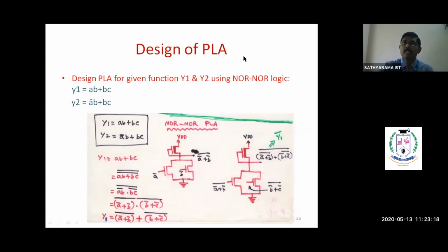Okay, so here we are going to make the NOR logic by using only NMOS inverter logic. We should not go for static CMOS logic. We make only NMOS inverter logic, because in the case of only NMOS inverter logic we have fewer transistors. In this NMOS inverter logic, we have the depletion mode transistor and the gate is connected to the output.